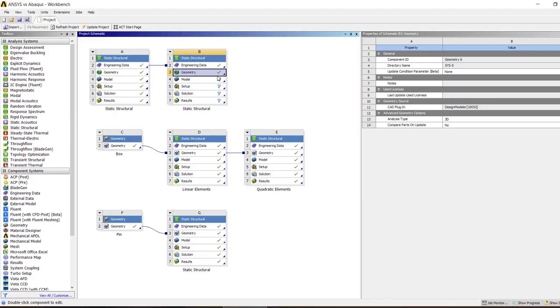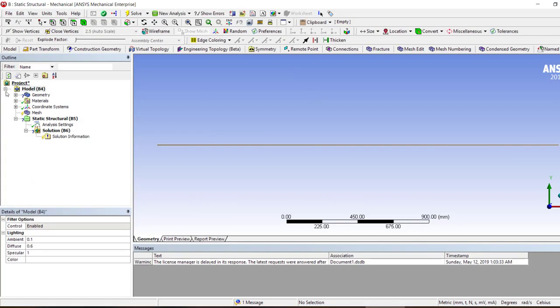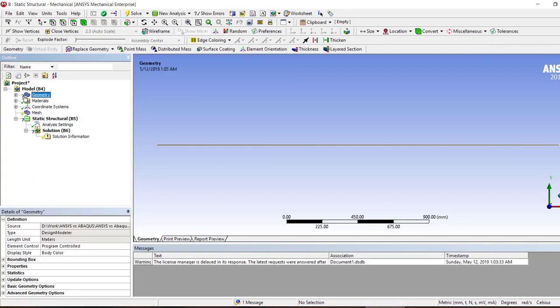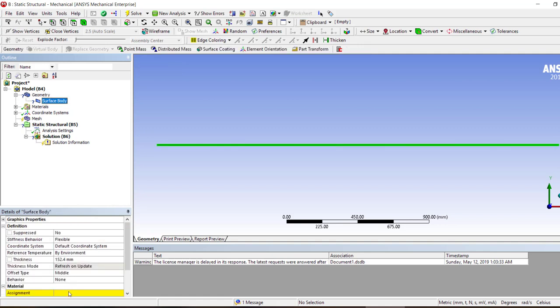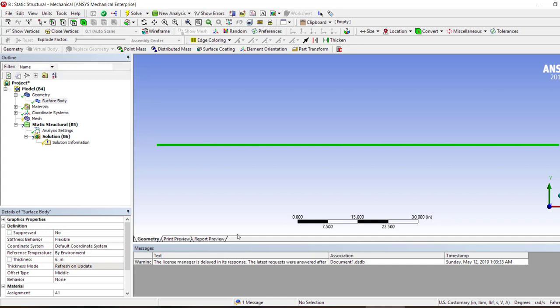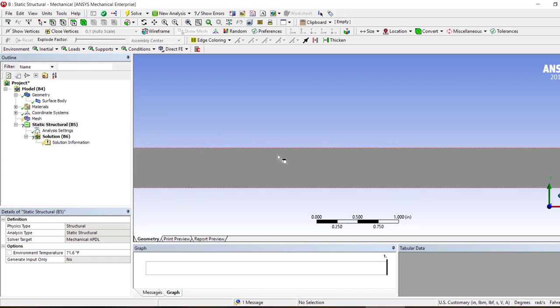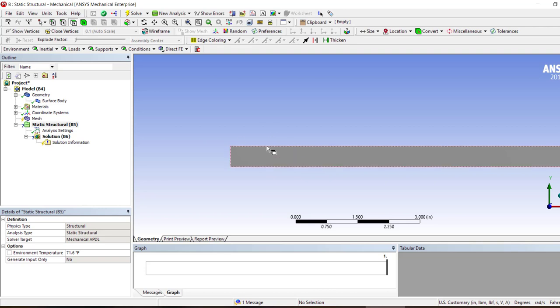So let's go to the meshing, and as you can see, there is a question mark over here. Something's wrong, and the assignment is A1, and the thickness here is going to be 6 inch. Now we didn't partition it. In ANSYS, this is the problem: you cannot partition it or play with it once you have it here. So we're going to go back to Design Modeler and then partition it.